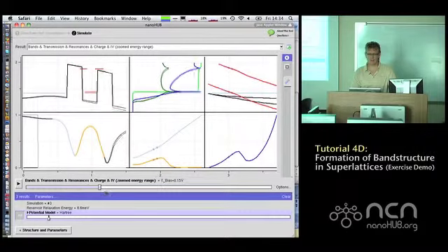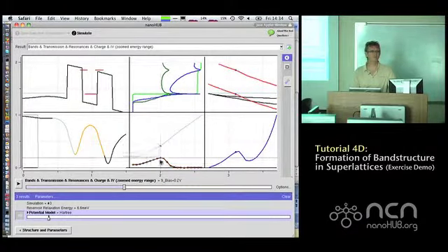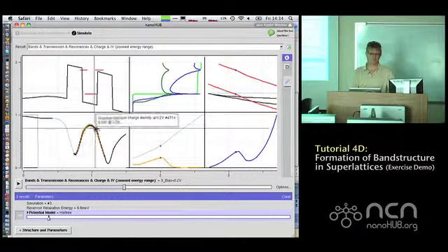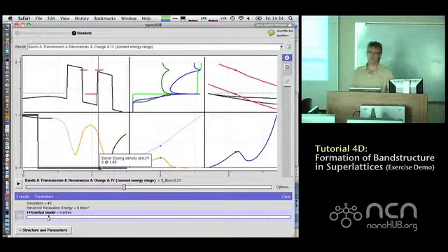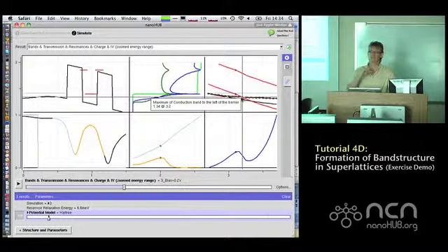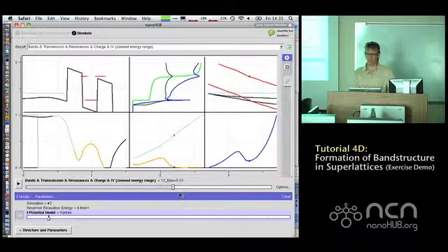We talk about how electrons are rattling around in the resonant tunneling diode. That means they're present, so there's charge in there. And that charge wants to get repulsed electrostatically, because it's more charge than belongs, since the doping is down here, but here's the charge. So it likes to reject that charge out. What happens? This resonance is moving not perfectly linearly, but it's a little bit pushed up. And then eventually the well empties out and the resonance falls down.